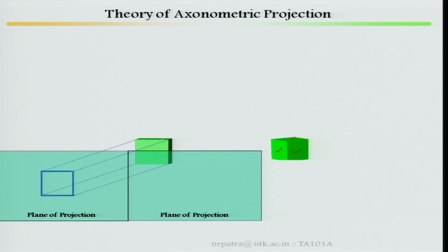Now in this way, if you look at the plane of projection, how does it look when I project it back? Here the moment I project it back, the projection is only the face. Here the moment I project it back, face, side as well as some part of your top surface. How it looks: here it is the front face, but here it is the face which I am visualizing. That means in the 3D view, three surfaces I am visualizing and it has been projected.